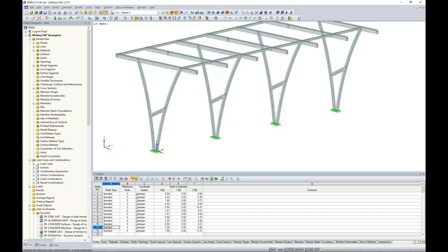I scroll to the next load case, impact 2, and you'll notice that my option to apply loads is still active. So I can just easily click on my column for the next load case to apply my second impact load. I right click to exit, and now you can see here as we scroll to the two different impact loads why we wouldn't want these acting at the same time, but rather we wanted either one or the other. Now, of course, maybe we'd want to add some impact loads to our exterior columns as well, but we'll just keep that for the simple application for today.